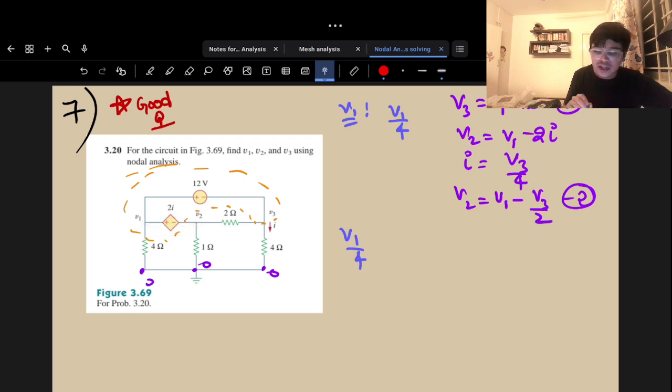That's why I was thinking to solve by taking the supernode, but I tried to think of another method that can maybe make it more simplified, but at least for right now I can't think of one. Okay, so this is my internal current. You can either do the algebra and cancel them, or you can simply treat them as internal current and not write them. So there is one current entering into V3 from V1, and that is going to be on one side, and it is equal, so this is also going to get cancelled.